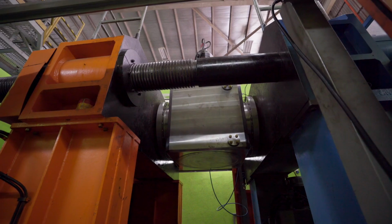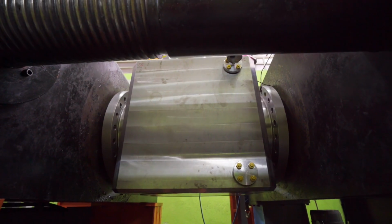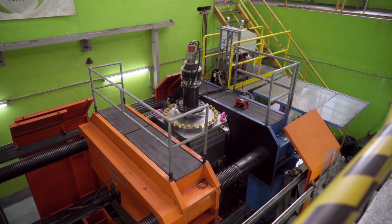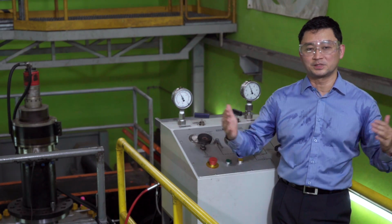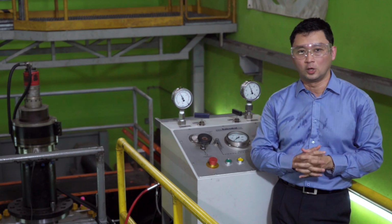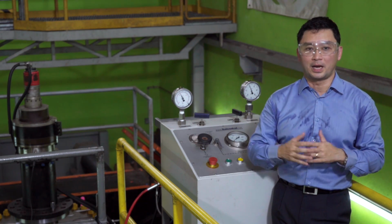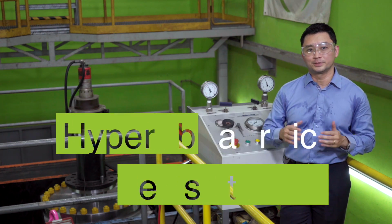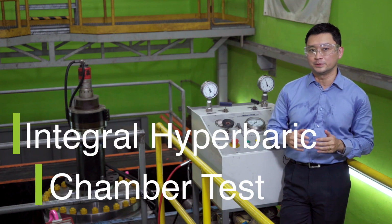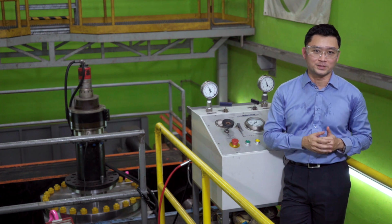Now, this is a subsea valve, which means that it is going to be installed immersed in the ocean. Subsea valves are made with environmental seals, which keep the seawater from getting into the valve. Obviously, the deeper the valve is installed in the ocean, the higher the pressure the valve will experience. Here at MIR-Valve, we have come up with a way to test the environmental seals without the use of a hyperbaric chamber, by building the test facility into the valve itself.